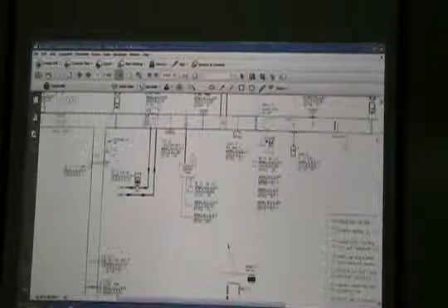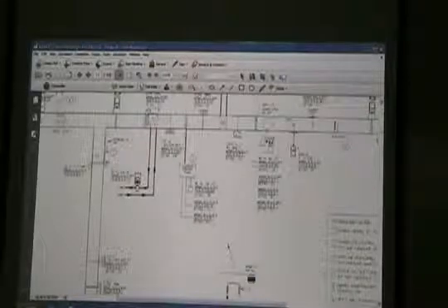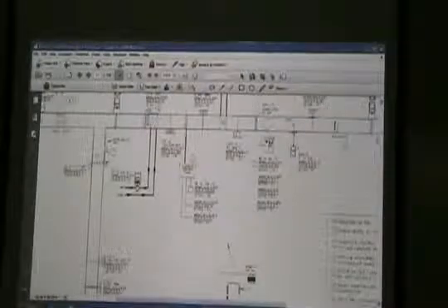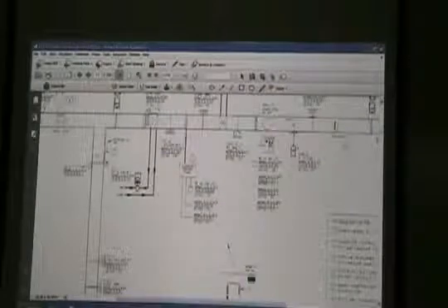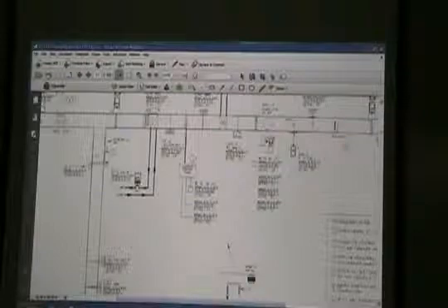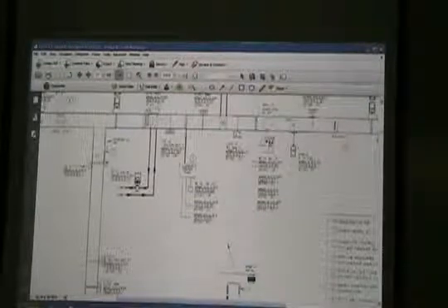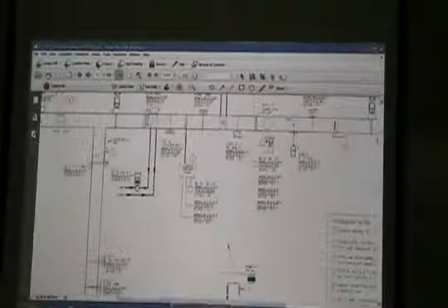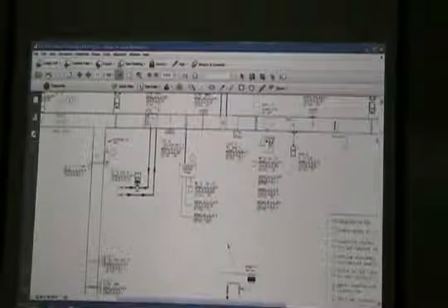Yeah, so we didn't take this wire straight into the humidifier. The humidifier is probably capable of controlling itself. So we've got an enable device to turn it on and off. We've got a signal device, which is going to be a digital output, on and off. This is a signal device, so it's going to be an analog output. It varies the signal to this humidifier based on what this is telling us right here. And then we've got an alarm, so a digital output back to our controller for an alarm point. Now the humidifier high limit.